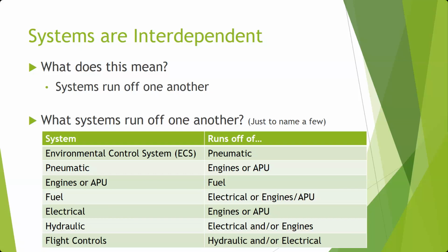Okay. Is anyone taking a look at the 727 out there, for instance? What happens to the flaps when it's just sitting out there? They're drooped down. What happens to the elevator when it's just sitting out there? It's drooped down. What do you think happens as soon as you turn on hydraulic pressure? They all go back to streamline or they get sucked up. So if somebody's working in that area, not good.